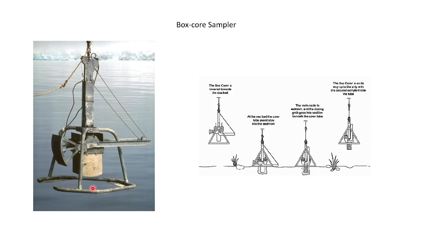Now this will come and cut, and whatever length or height it has penetrated will be contained as the sample. This will be released by some mechanical system, cutting the sample from the bottom, and then it will be lifted out to the vessel. And once the soils are lifted, you can do the tests.